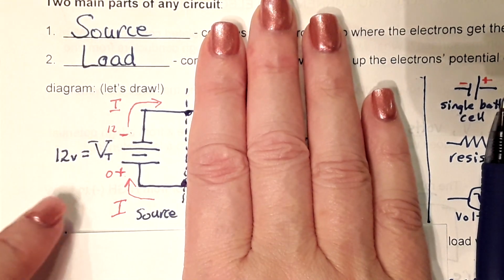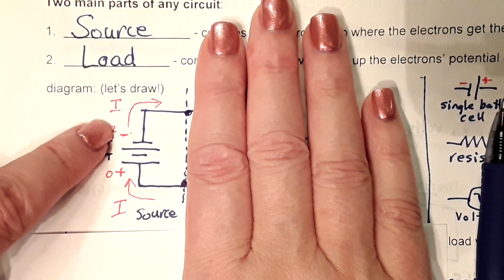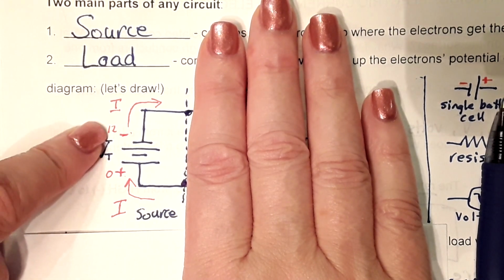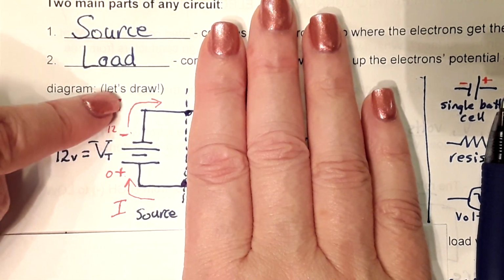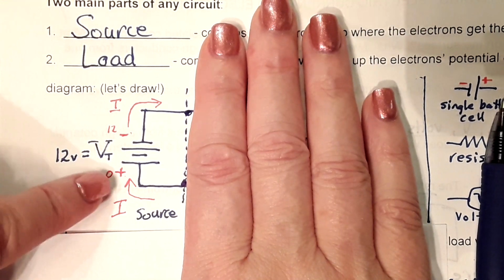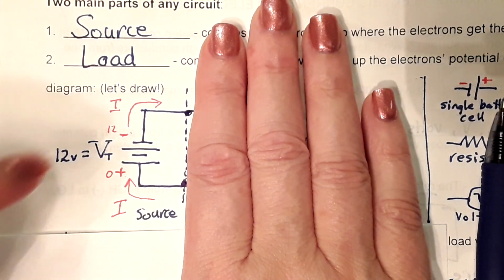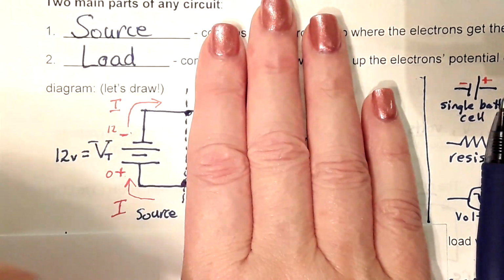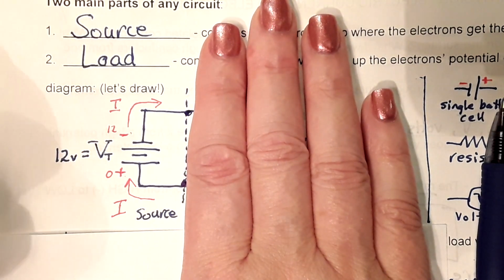So this battery is a 12-volt battery. That means the high potential side has a maximum of 12 volts. The low potential side is 0 volts of electric potential, okay? The current is going to start on this side and go all the way around through the circuit and end up back here, where it will have nothing left. All 12 volts of potential will have done work to go through the devices and drop off energy, and then they come back here and the electrons get pumped up again.